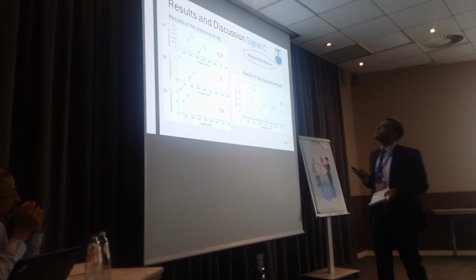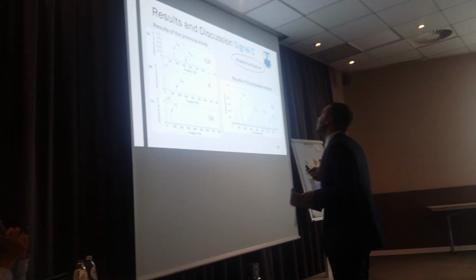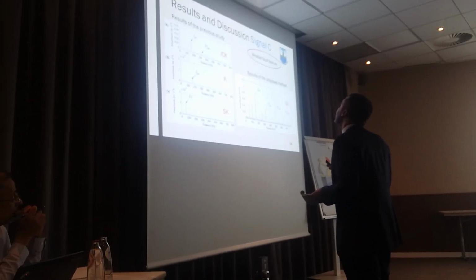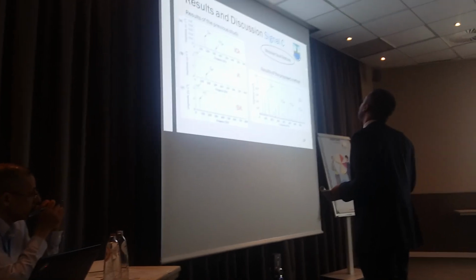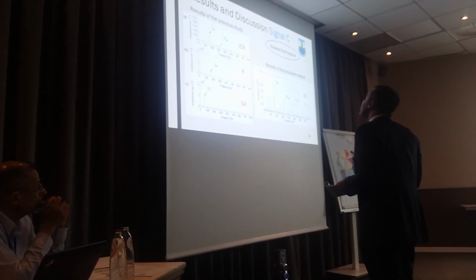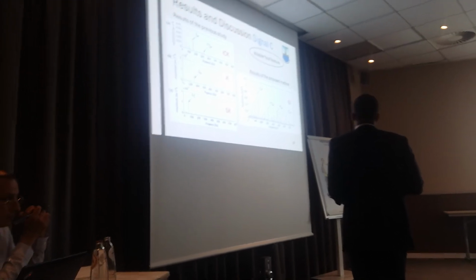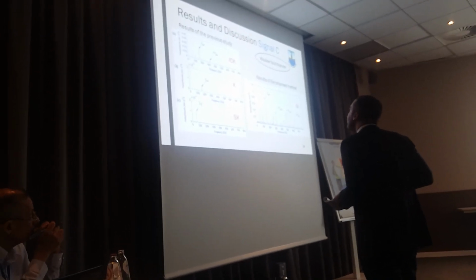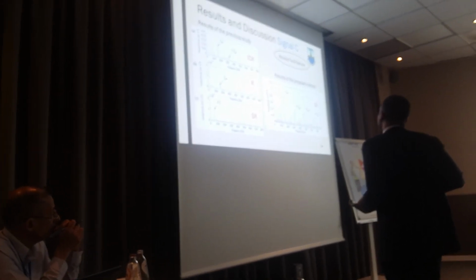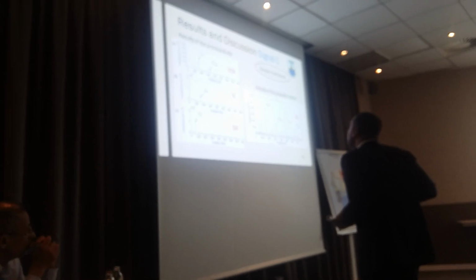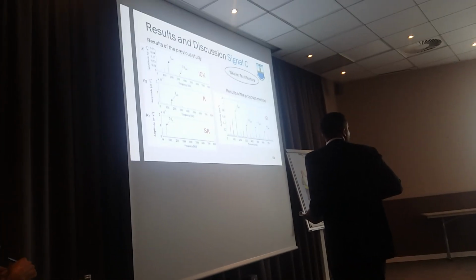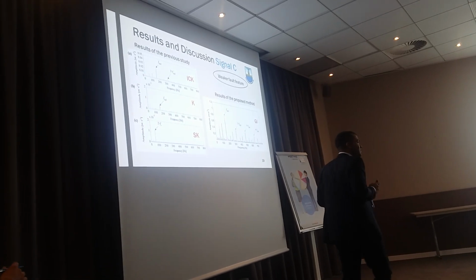In the previous study, the squared envelope spectrum obtained based on the improved correlated kurtosis showed up to the second harmonic of the bearing characteristic frequency, when kurtosis showed only the first harmonic, and the spectral kurtosis failed to show any amplitude at the bearing characteristic frequency.